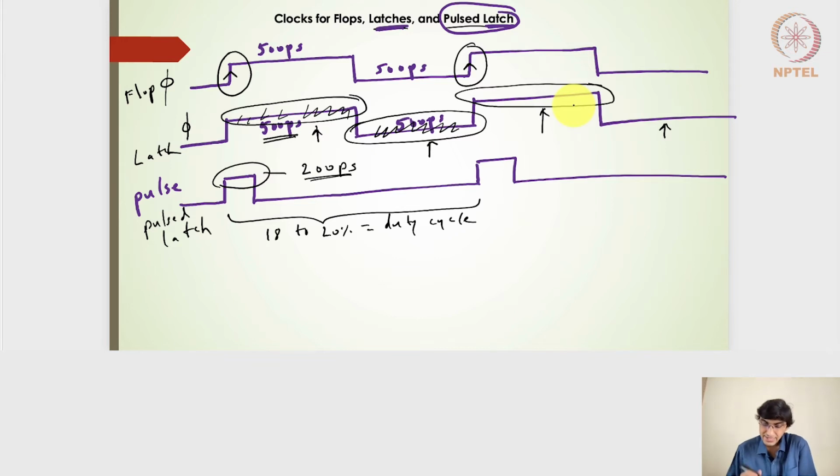Whereas in the pulse latch, this particular latch closely follows the flop designs. Also, we don't have that kind of tighter constraints. But at the same time, whatever combinatorial circuit data path we choose, the similar thing will remain for the pulse latch. So if I'm designing a combinatorial circuit here, its output should be captured in pulse number 1, and then it will go to the subsequent combinatorial circuit, and that should be captured in the second pulse.